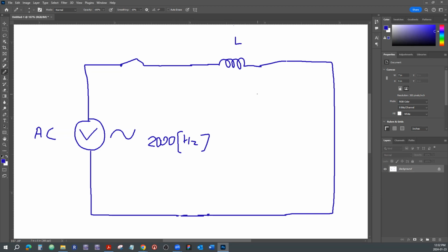So, what can we say? As opposed to a pure resistor, whose resistance will not change depending on the frequency that you apply through the circuit, the coil is not going to act like that. The coil is going to give you more or less resistance depending on the frequency that you apply. The greater the frequency, the more resistance it's going to give you. So the resistance is reactive accordingly, and it depends on the frequency that you apply.